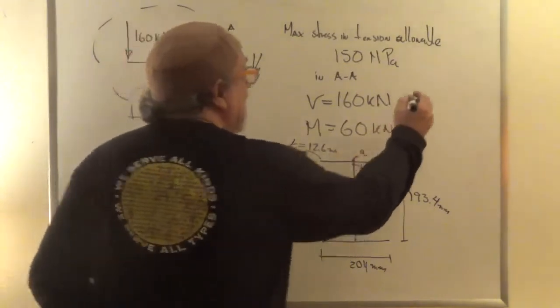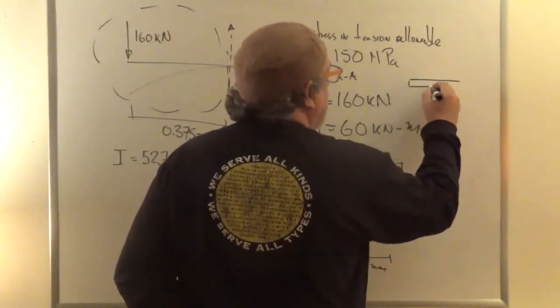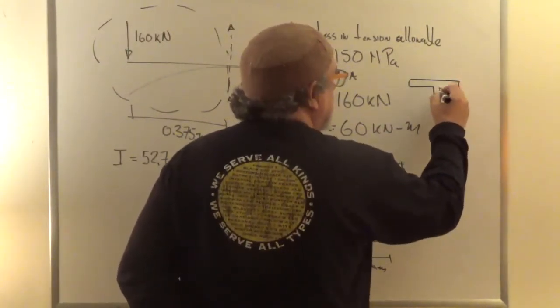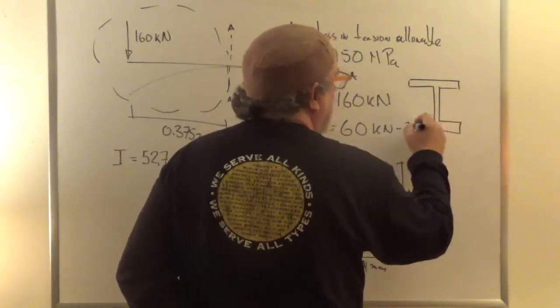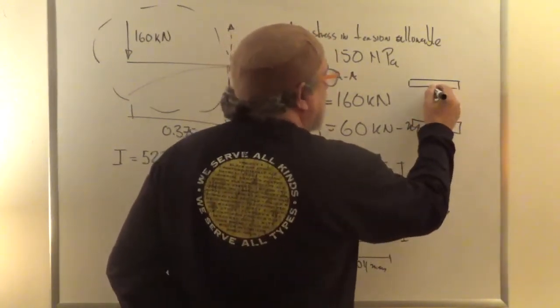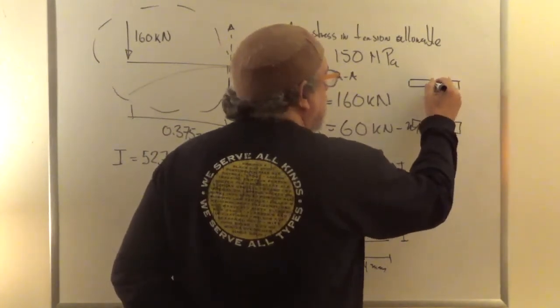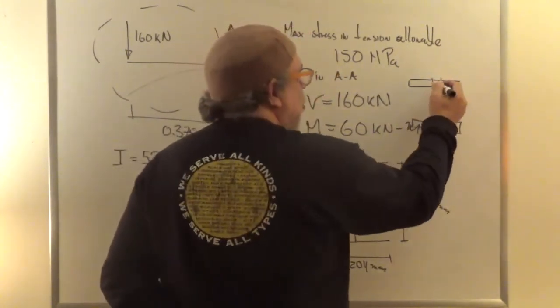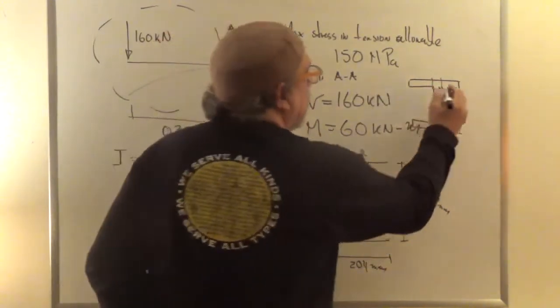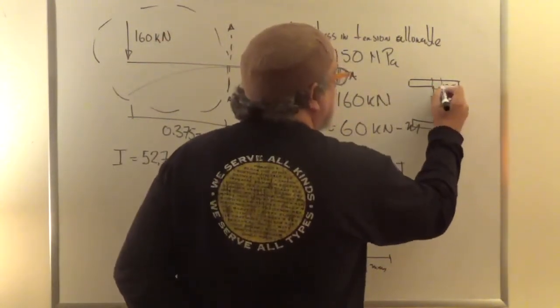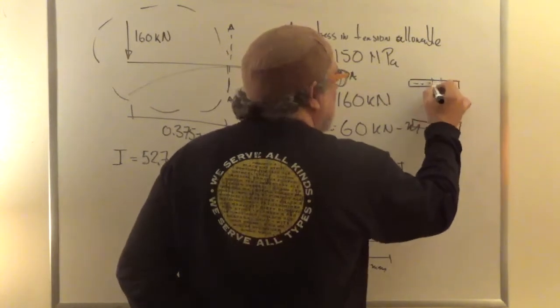In actuality, it's kind of hard to talk about point A and point B because the situation is like this, so what you have is a joint there. Stresses are clear. When we calculate shear flows, we can get them up to here, but what happens in the joint is not well defined. So we can get our shear flows like this and like this, but in here it's not so clear.